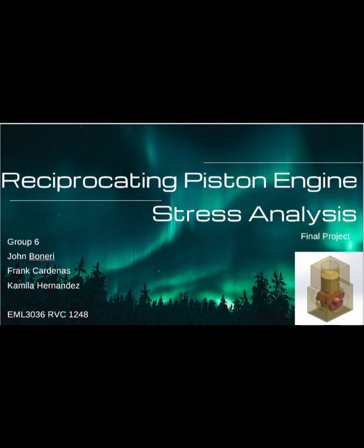For the analysis of our engine, we used 8.5 megapascals, which when converted to force using the top area of the piston, is approximately 54,074 newtons, which we moved up to 54,200 newtons to put the parts under more difficult conditions. Under this force, we analyze the parts under their worst condition, which is typically when the piston is either at bottom dead center or top dead center.